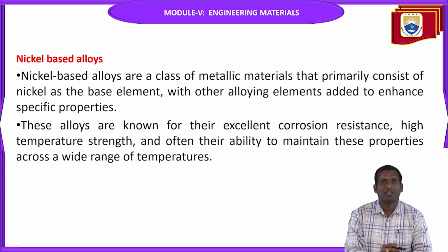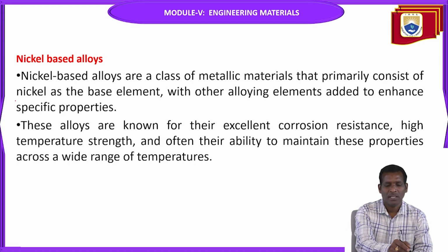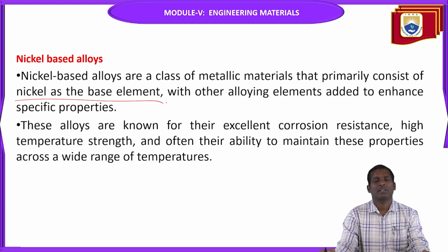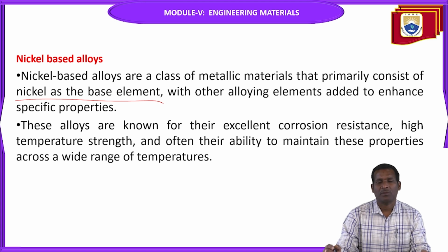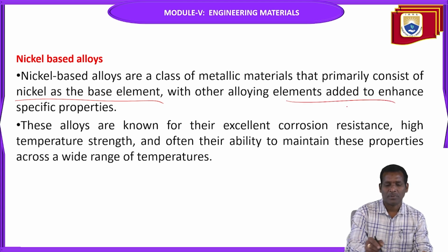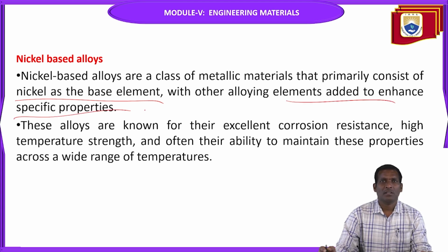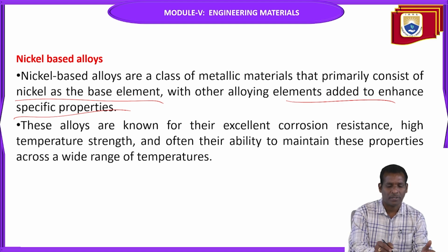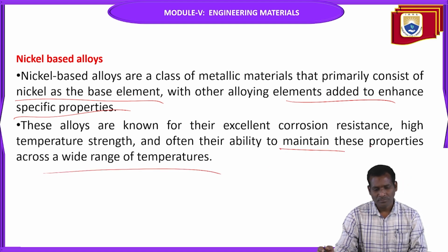The nickel-based alloys are a class of metallic materials that primarily consist of nickel as the base element. Here, nickel is the base element; in the previous case, aluminum was the base element. Other alloying elements are added to this nickel-based metal to enhance specific properties. These alloys are known for their excellent corrosion resistance, high temperature strength, and often their ability to maintain these properties across a wide range of temperatures.